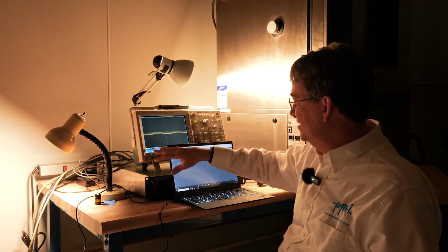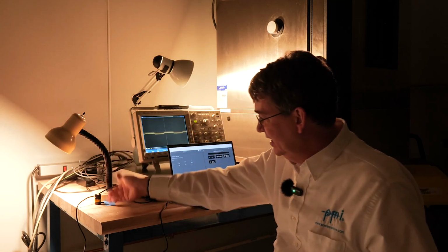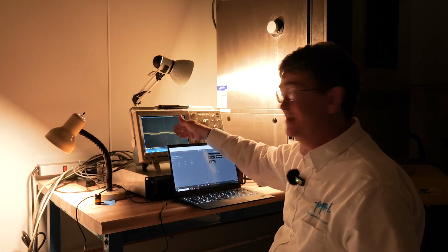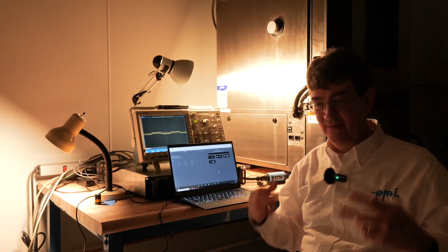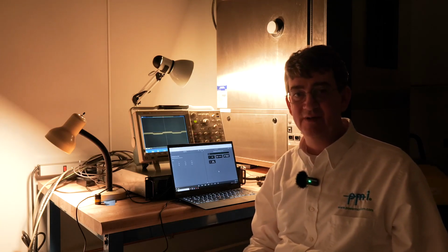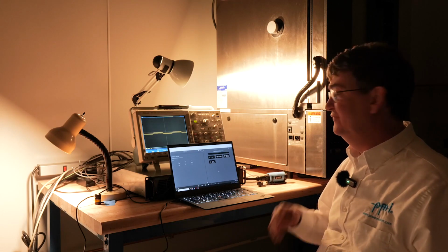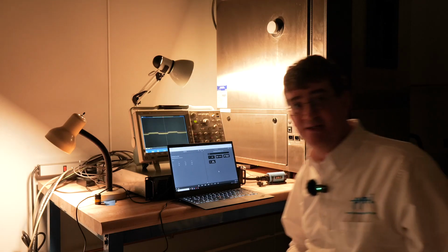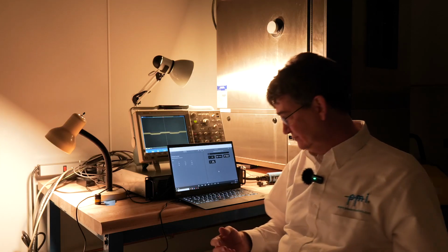And to verify our setup, we have two incandescent bulbs powered from the AC source and an optical sensor feeding into the oscilloscope as a separate measurement of the amount of optical light change output from the filaments when we subject it to different RMS voltage variations. You can see the flicker now. We are actually around a flicker level of 2, which is twice the threshold of irritability per IEEE 1453.